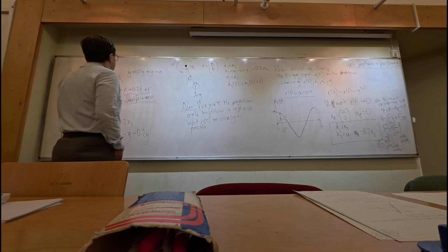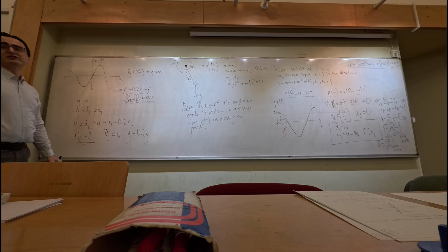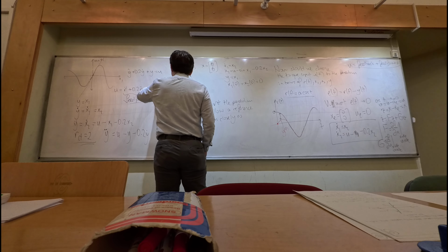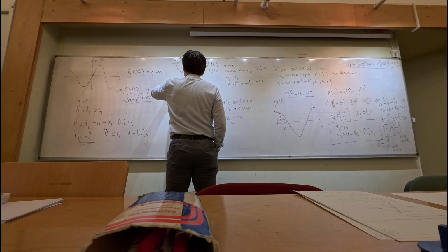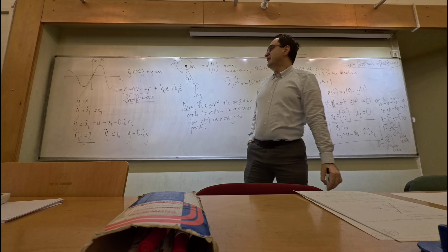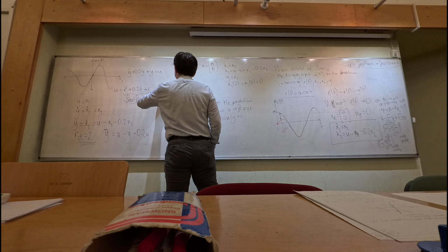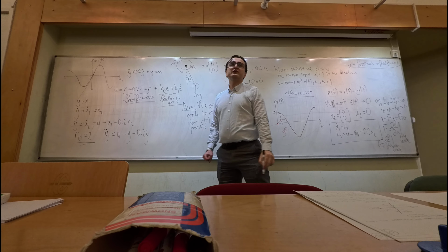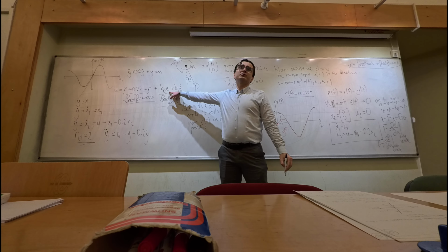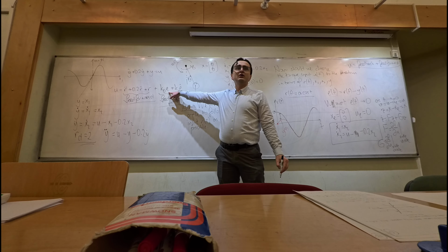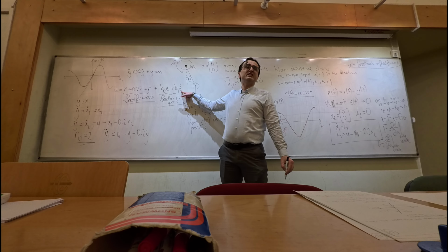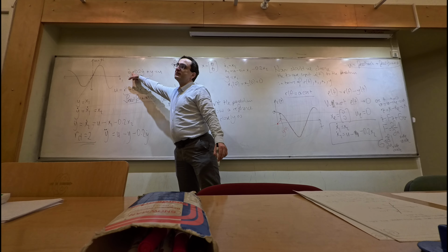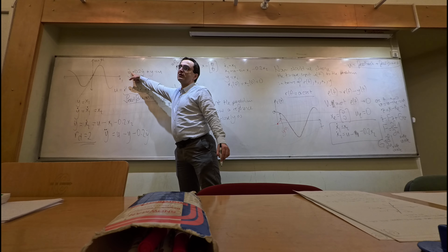The second part is related to the feedback controller part. I will write the second part as k0 times E plus k1 times E dot. This part is called the feedback part, and it is formed out of the error signal. Here I will continue including the derivatives of the error signal until the order one less than the derivative orders on the left-hand side.